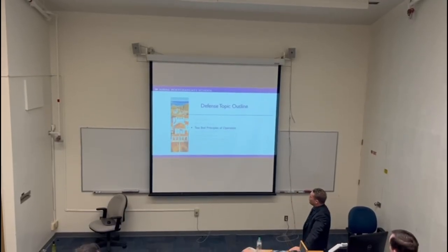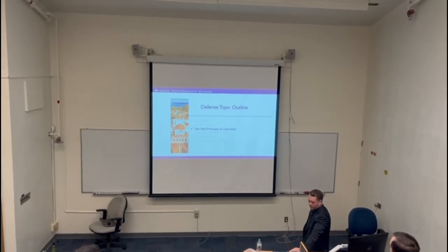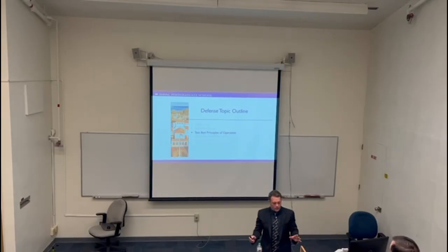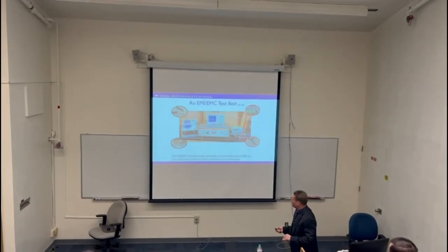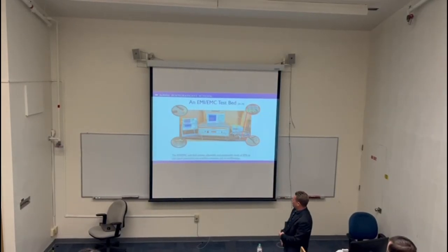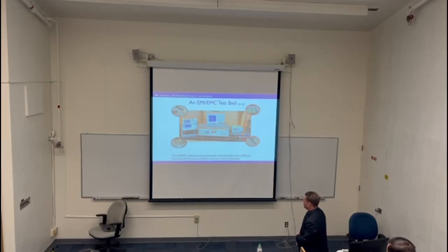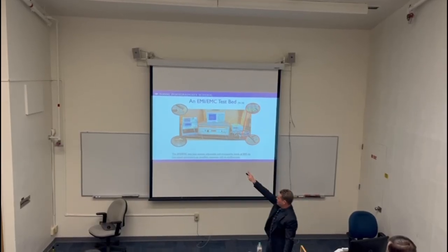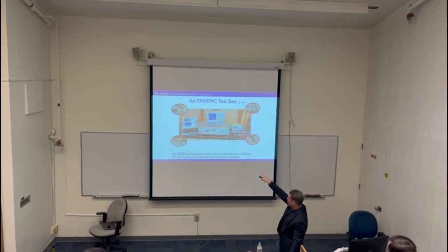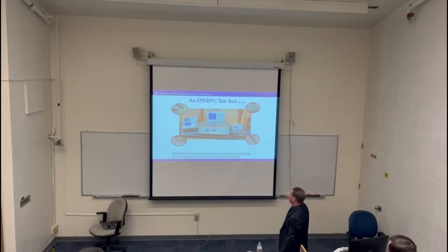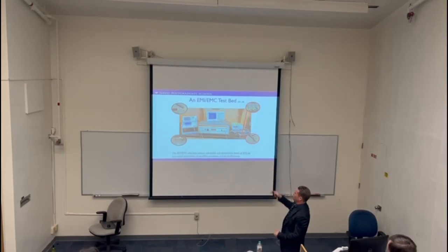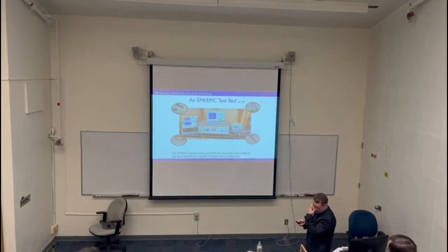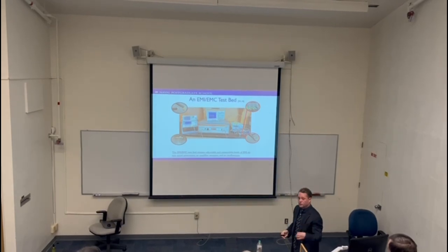All right, so now we're on to the actual test bed. I didn't actually bring the entire test bed in, but I brought at least a little picture here to give you a rough idea. Essentially, it's a couple of signal generators. You can see them on the top left there. A power amplifier, an AR 100-watt power amplifier. I have an oscilloscope to look at the modulated waveform that I'm putting out, that creates a non-destructive type of waveform to inject into the EUT.